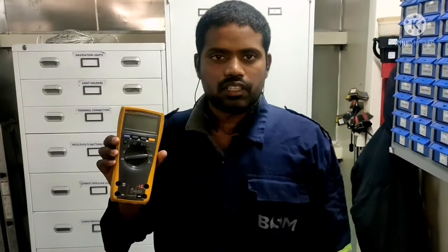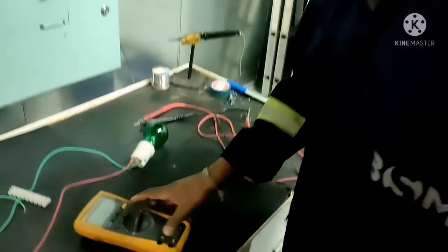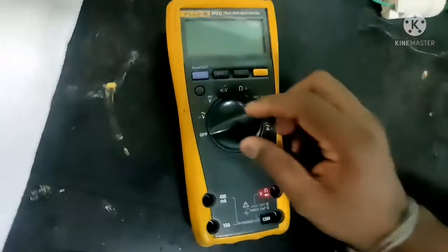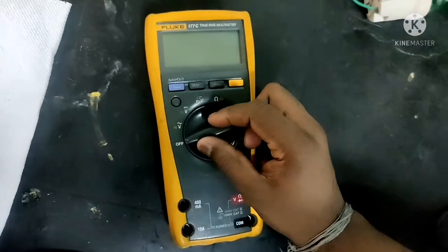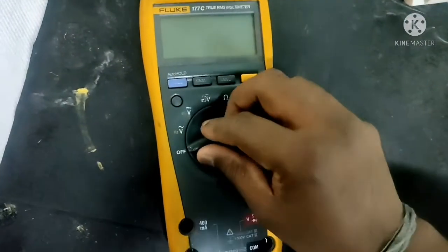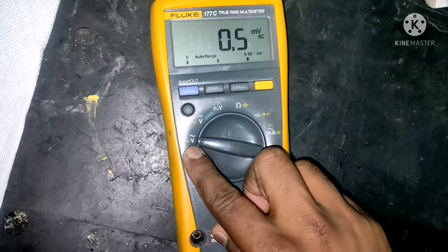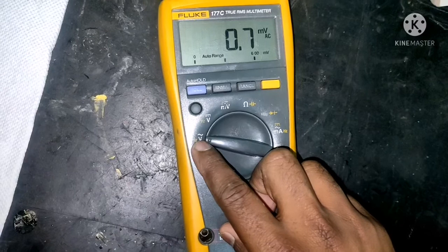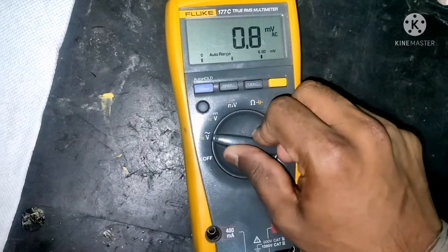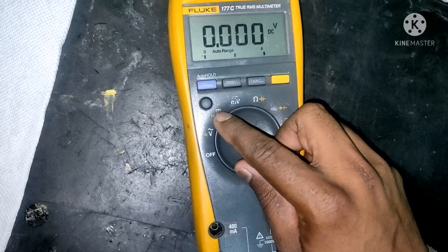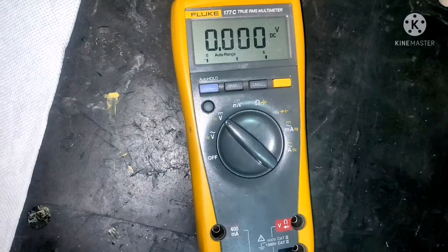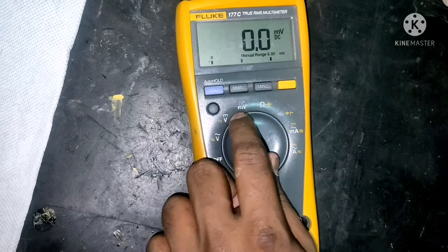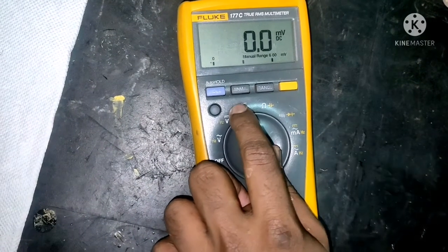Hi friends, today I'm going to explain how to use a multimeter. This multimeter has a selector switch, and you can select whichever function you want to check. Suppose you want to check the voltage, you can select that particular point. Just turn the selector switch and you can check the voltage, and you can see the sine symbol which indicates AC, and next will again be a voltage, and it indicates this symbol, one line with dots, which indicates DC, and this is millivolt, again that is for DC.